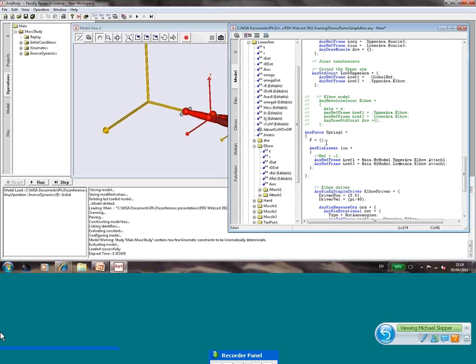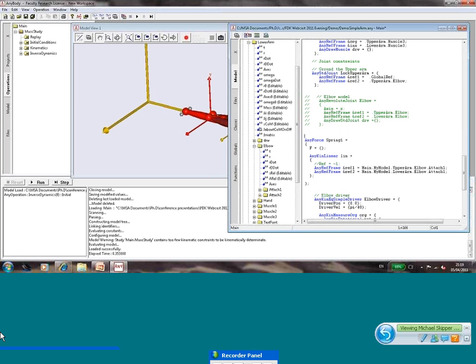So what I want my force to be is some stiffness times the length of this vector. And I will define an AnyVar, and I will call it stiffness, so we actually have global access to it, and I will just for now set it to 1000, just to start with a value. So the 3 components I want is my stiffness